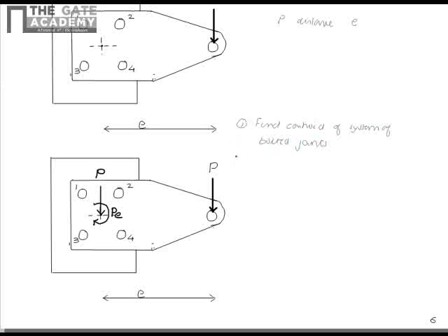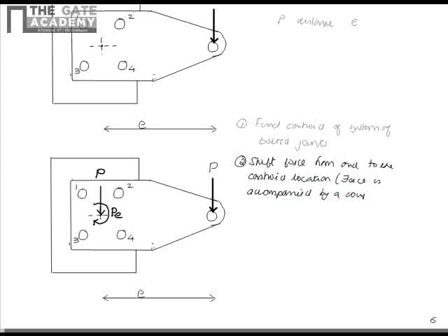And the second step would be to shift the force from the end to the centroid location. In that case, the force is accompanied by a couple given by force into distance.